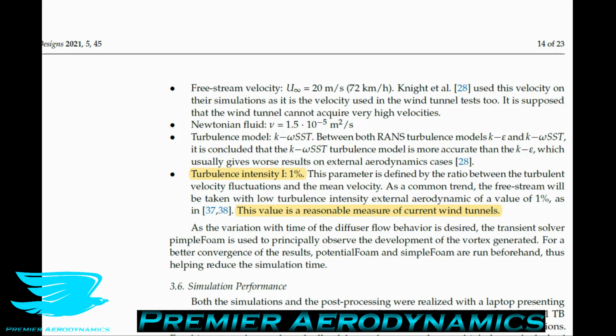So it depends on where you are in your driving phase, what the boundary conditions and environmental conditions are, and how fast you're moving. It would depend on the turbulence intensity that you need. So 1% is about an average turbulence intensity level across your race, I guess you could say. But it could be a lot higher, it could be a lot lower.